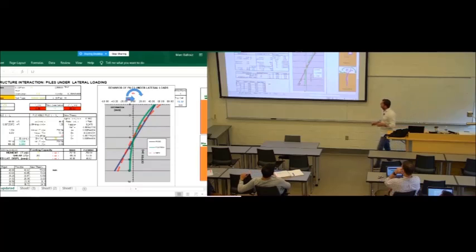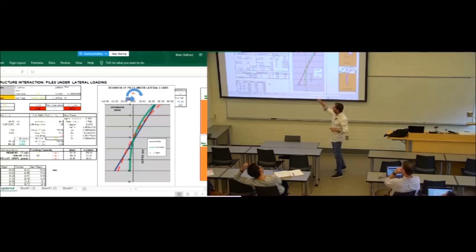The pile is 12 meters, and now it's somewhere in between 6 and 20, 3L0. So L0 is 6 meters, 3L0 is 20. Look at the red line. Look at the surprise. The deformation is more than both theories. So if you interpolate between both, you are wrong.